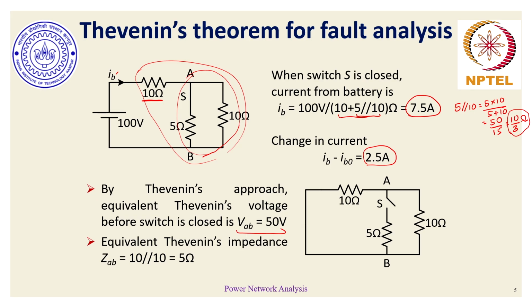Why are voltage sources shorted while finding Thevenin impedance? The answer is simple. When I'm finding Thevenin's impedance, all my sources should not deliver any quantum of energy or power. When I short my voltage source, the potential across that source itself is zero, so it won't be able to deliver any amount of power or energy, and none of the circuit elements would be consuming any quantum of energy or power from the voltage source. So basically I'm trying to make my voltage source as passive as possible.